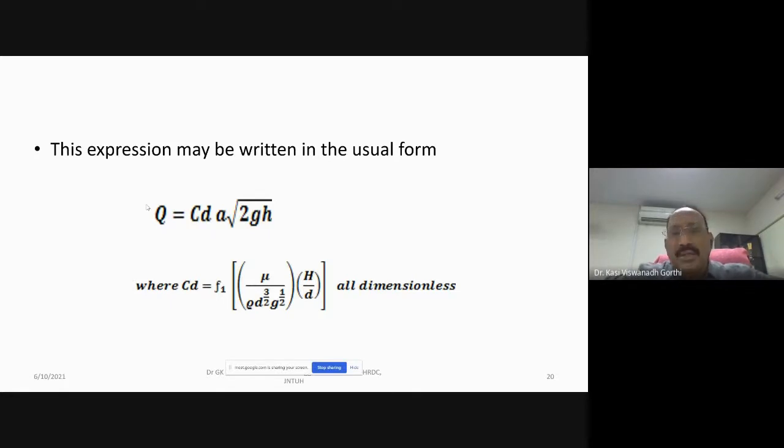Because in this mathematical technique, we use a very set procedure. The set procedure is so simple: identify the dependent variable, identify all the independent variables, establish a functional relationship, form an exponential equation, treat that exponential equation as a dimensionally homogeneous equation, write the dimension formula for all the variables involved in that exponential equation, then group the powers of the like terms, and then solve for the exponent variables.